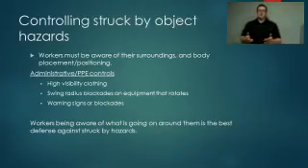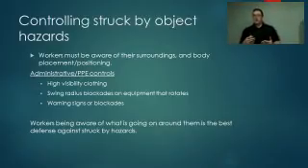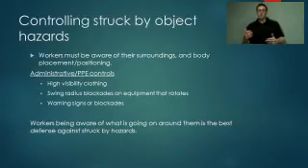One of the biggest things that's always taught when talking about struck by object accidents is body positioning and placement. If I'm walking around a job site, I need to be sure that operators can see me, especially when you're walking in blind spots, behind them or areas of the machine where components of that machine itself will impede their view. You need to make sure that the operator sees you before you try to move around them, and that can mean making eye contact or waving.